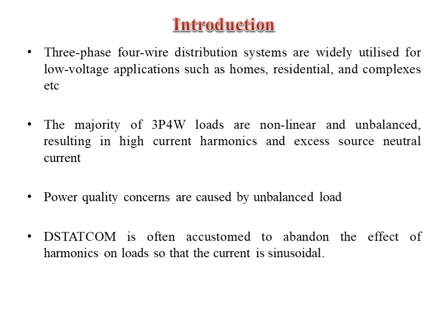Renewable power sources are used to generate electricity and are supplied straight to the network to take care of the grid voltage and sturdiness. Compensation plays a big part in absorbing the network's reactive power. The shunt power compensator, that is distribution static compensator, is connected in shunt at a common point, that is PCC, to compensate for both categories of power quality problems.